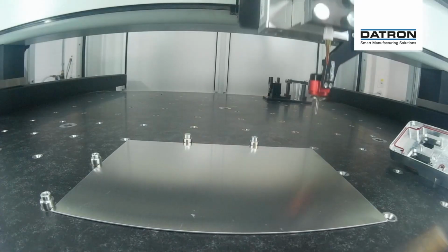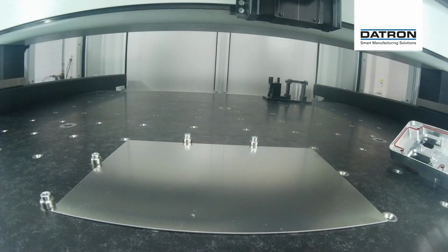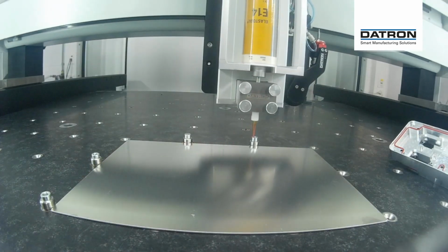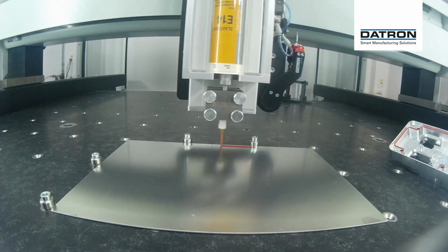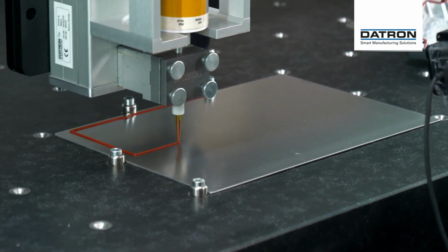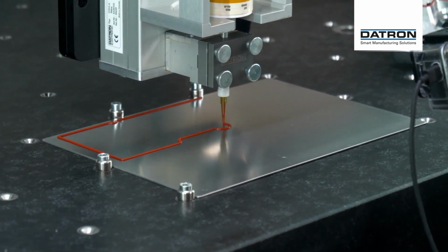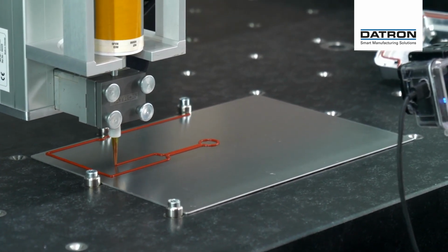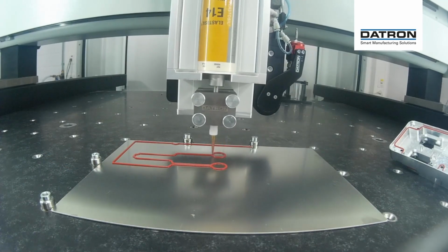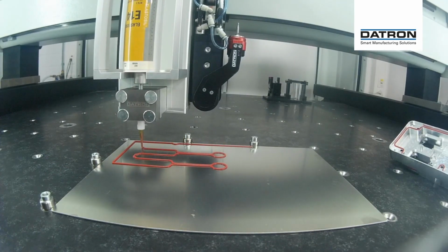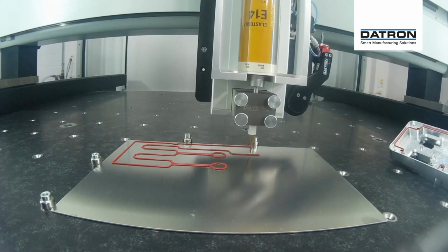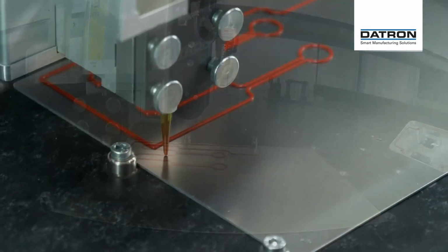So now we are finished with the measuring. The machine knows the overall surface height and then starts to dispense. We are dispensing very fast here, and as you see, we have some corners where the machine has to reduce the speed. Even so, we always have the same amount of material everywhere, even when we are accelerating or decelerating. At the same point, the volume is exactly the same.